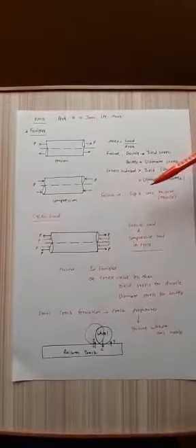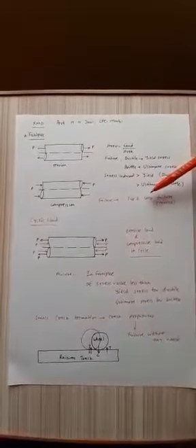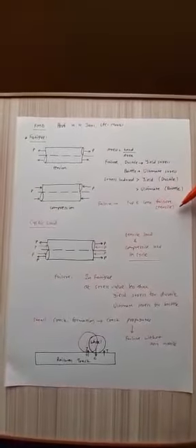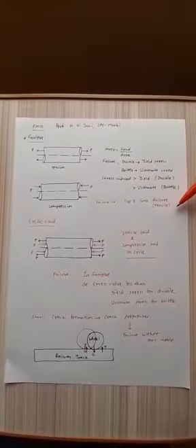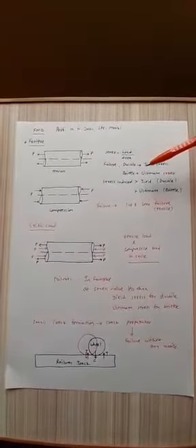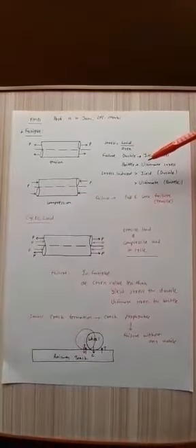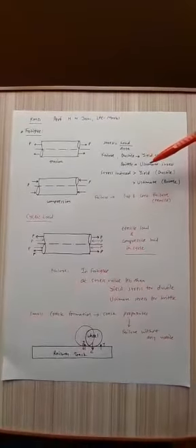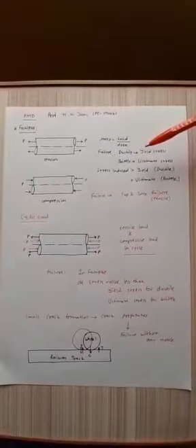When the load increases, there is cup and cone failure in the case of tensile application. So there is a notice. The cross section reduces and it gives us notice before the failure occurs.